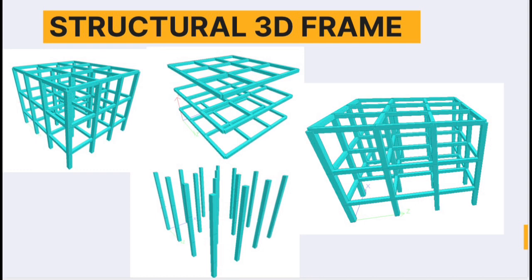The total floor area of the building is 180 square meters spread across 2 floors. We made sure to follow the minimum structural requirements as stated in the building code. Each column in the design has a prismatic size of 350 by 350 millimeters, ensuring sufficient strength to support vertical loads. The beams are sized at 250 by 300 millimeters, which offers a balance between structural integrity and cost efficiency. The dimensions are optimal for a residential building of this size and layout.